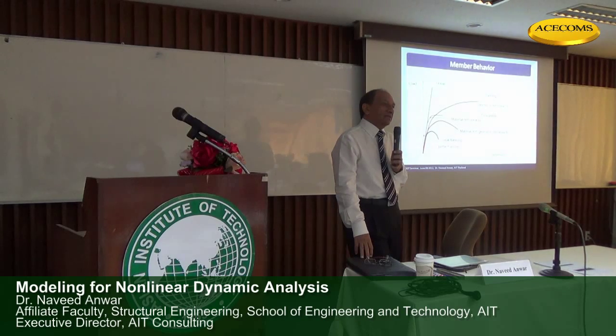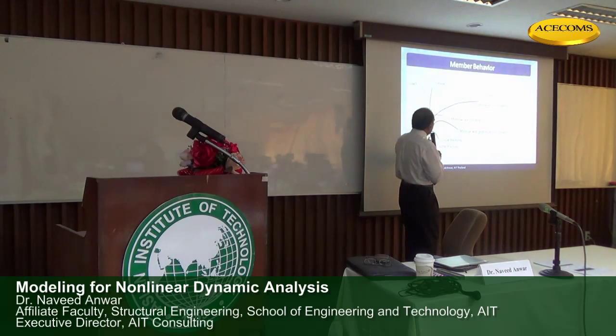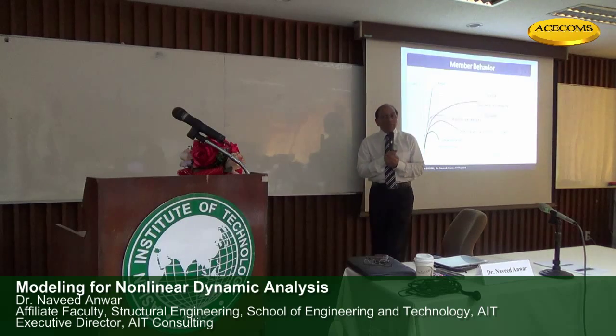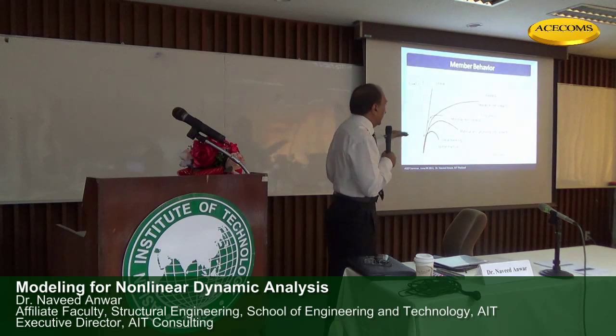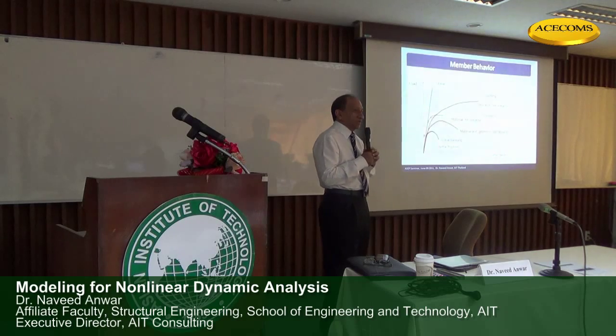But when we combine them together, then we have a complex nonlinear response of the member. So typically, we need to combine material and geometric nonlinearity. So we are talking about this kind of curve. That means it will start well, then slowly the deformation will change at a faster rate, then you'll have a flatter line, then it will go down, and somewhere it will stop or fall down. So that kind of behavior we need to model and trace by including all of these, buckling, material, geometric, into that total response.